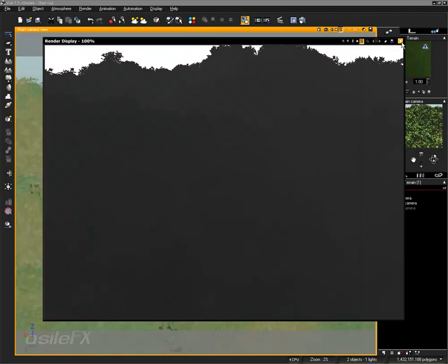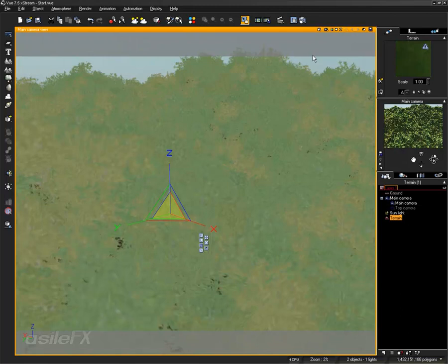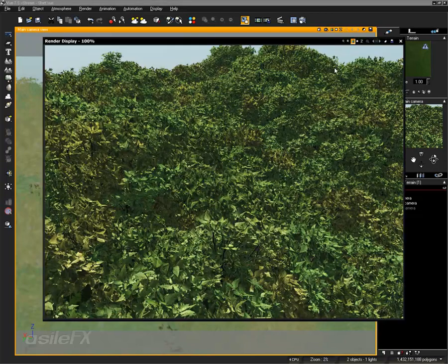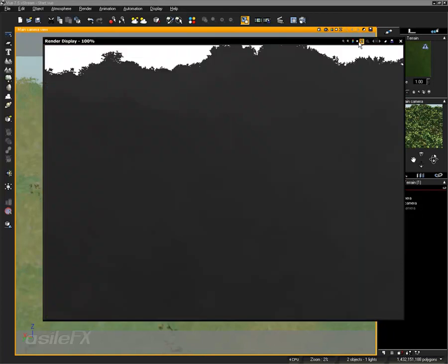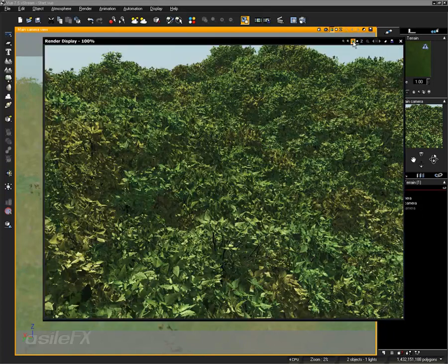And when you close out the render window, when you have it set to render to screen, you can bring back that render at any time. If you go to the top and select the channel within the camera view, then you can bring that render window right back up and go back through the last rendered image. Unfortunately, there's no other sort of saving where you have layers or different versions of renders that are stored, so just the last render is the one that shows up.